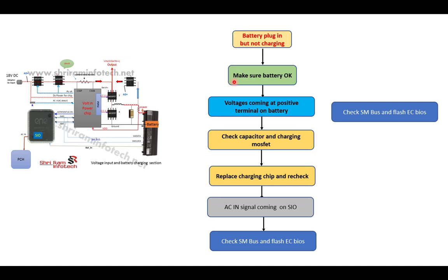Sometimes what happens is that there is no problem in the motherboard, there is a problem in the battery, and we are working on the motherboard and trying to solve the problem in the motherboard. But in that case, there's no problem in the motherboard, there's a problem in the battery. So make sure your battery is okay.